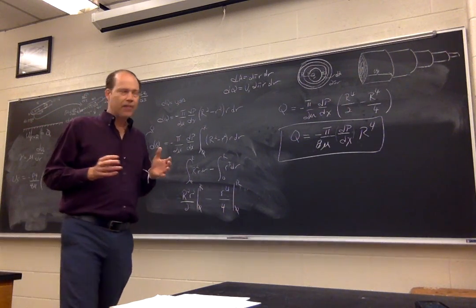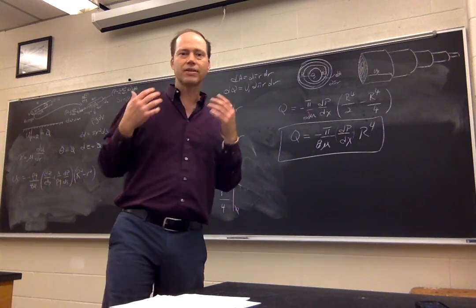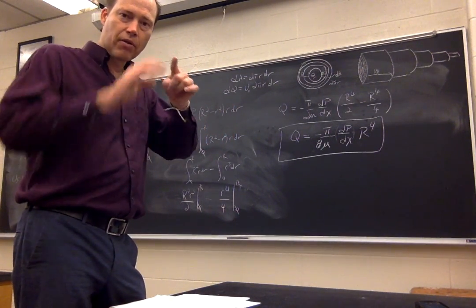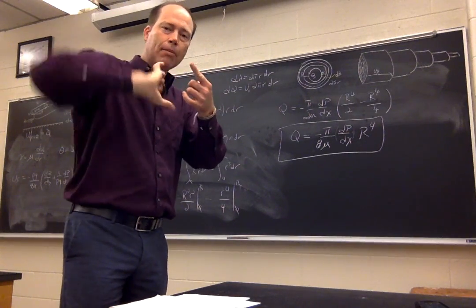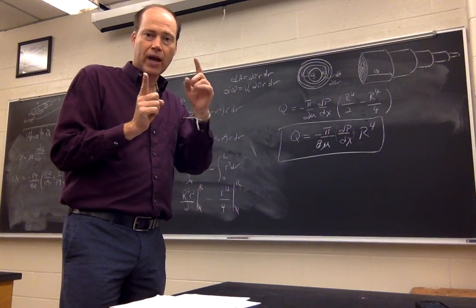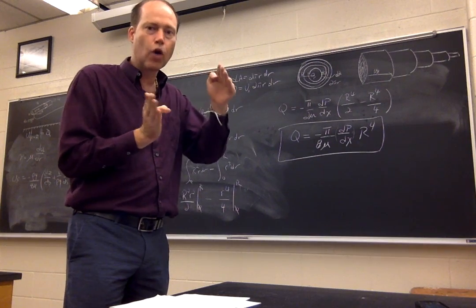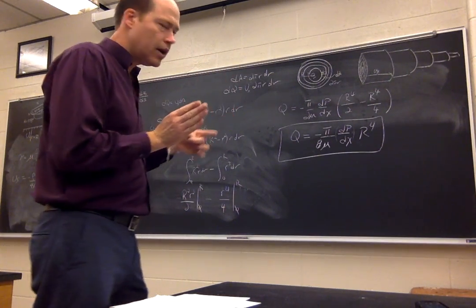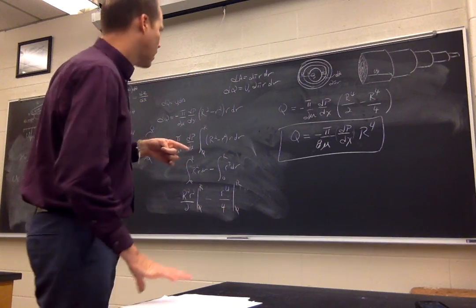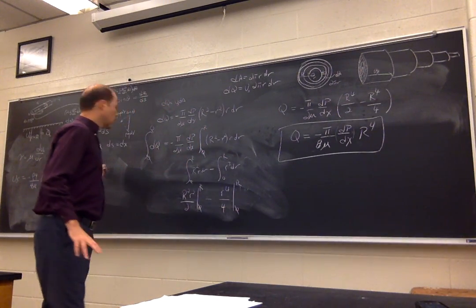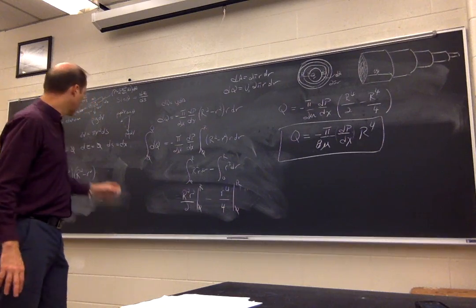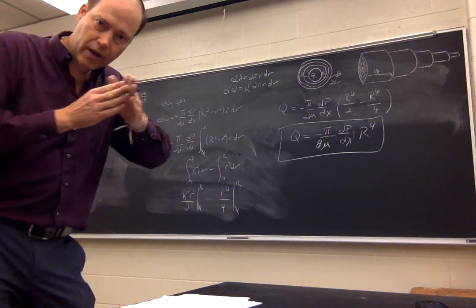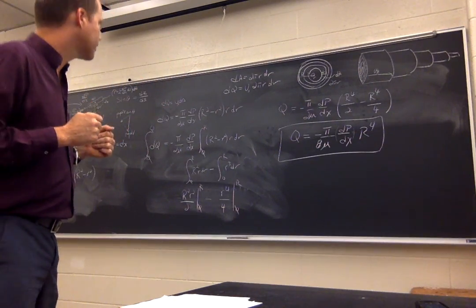cross profile. That velocity cross profile is exactly what we expect: it's fastest in the middle of the pipe, and it's shaped like a paraboloid, where in our system we have a no-slip condition where there's no flow on the circumference of the pipe, because that's where the shear stress is being applied. So we come up with a velocity cross profile where we can calculate the velocity at any point in that pipe, measured from the center moving out.